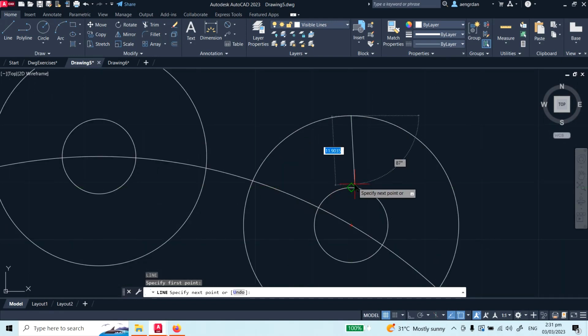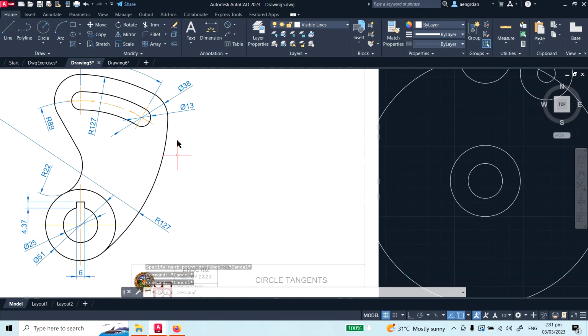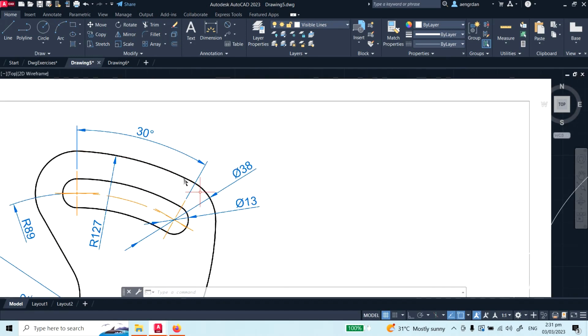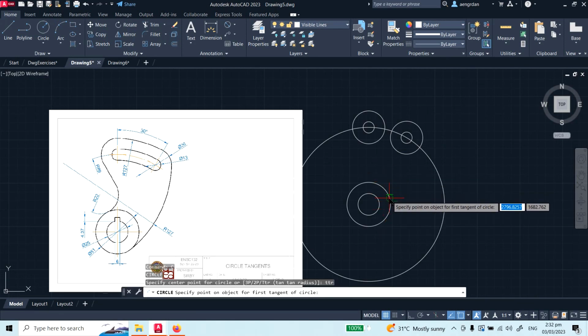So anyway, to continue, next we'll construct these TTR circles, 127 radius and 127 radius also over here. So type C and then type TTR. In specifying this, I think it will matter whether we're coming from here to there or from here to here.